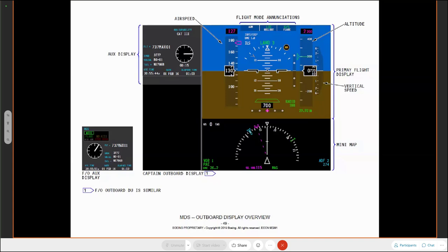So in this case, when you tune to a VOR, if it has a co-located DME system, it will automatically tune the DME for you. And the VOR will give you guidance. Okay, you can follow the guidance, select a radial, one of 360 degree radials, and then it will also show you the distance in slant range to that VOR in this case. Okay, ground speed, true airspeed. Again, this is information coming from your inertial reference system, and also the flight management computer has an input in this as well.